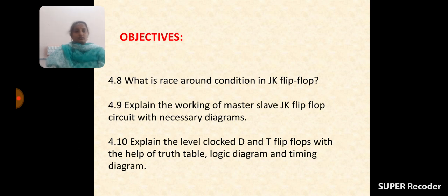And the remaining two, means when both the inputs are the same, either low or high, the output is not changed. That condition is called hold condition. What is the name of that condition? The condition is called hold condition. And see here, in the RS flip-flop, when both inputs are high, there exists a hold condition, and that hold condition must be eliminated with the help of JK flip-flop. How will it be eliminated? With the help of JK flip-flop.